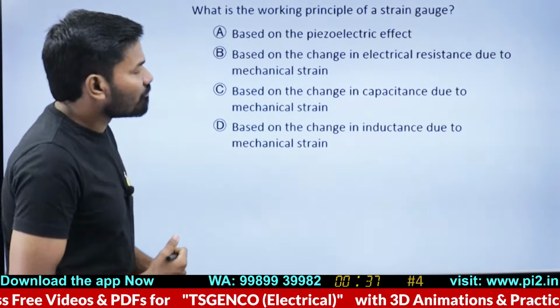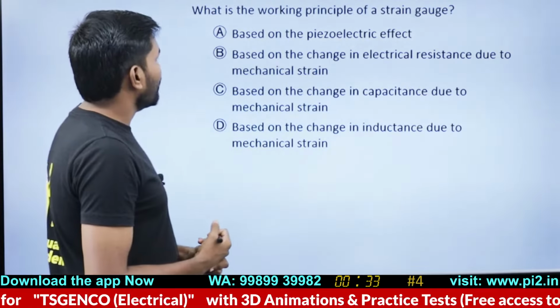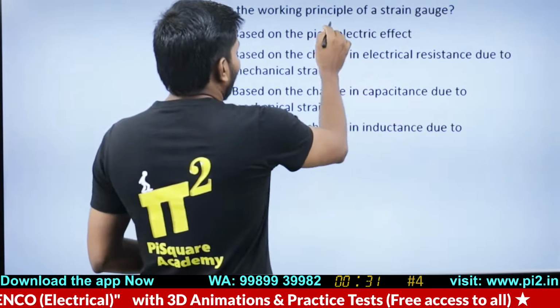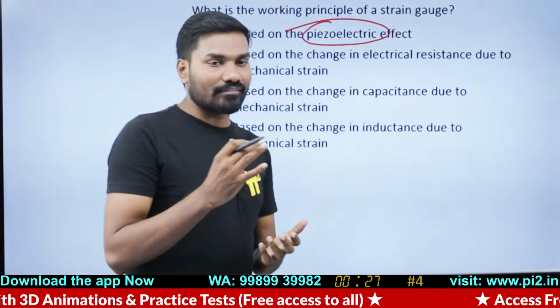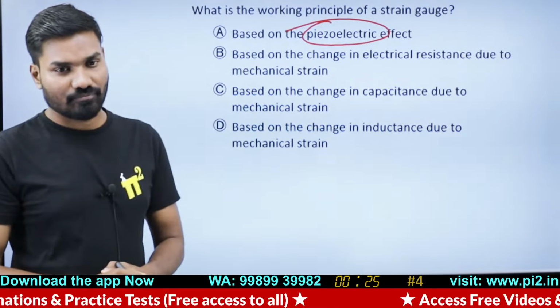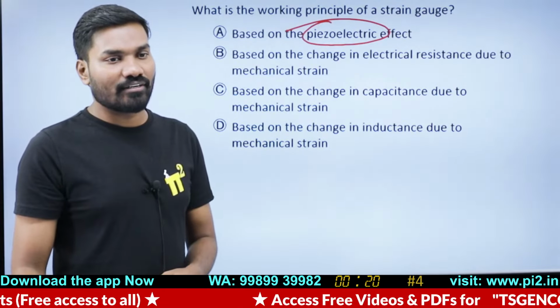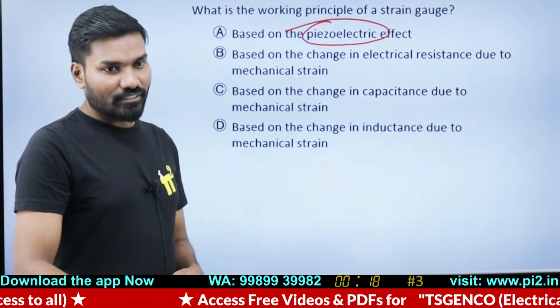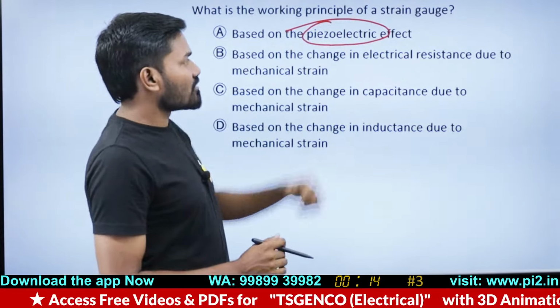What is the working principle of strain gauge? Piezoelectric effect? No, piezoelectric effect means it gives electrical energy. Is it giving electrical energy? No, it's giving change in resistance.